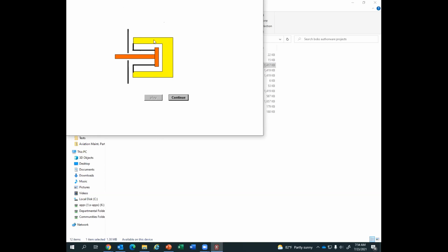But did you kind of see the yellow and the black come out and hit the pin? Yeah. Okay. Now, when I hit the continue button, it's going to indicate like the pads are wearing. So the yellow piston is going to move to the right. That's going to drag the adjusting pin to the right. But then when the pedal is released, the piston is going to move back and hit the pin. Ready? It moves it and then returns back. This is the standard when the brakes are released. This is what it normally looks like.